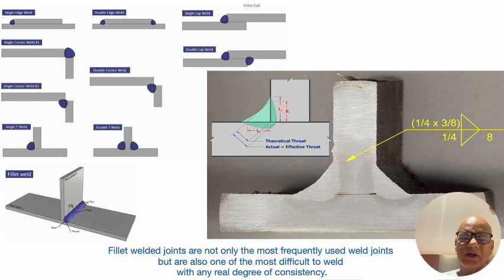and at the same time there are no defects. Like any other weld principle, if you cut right, you set right; if you set right, you weld right. That applies to the fillet also. We should put this vertical member on the horizontal member with as close a gap as possible, which means the edge preparation has to be cut correctly. The horizontal plate shall be as flat as possible, and we should fix it at 90 degrees, that is a right angle, on both sides, and tack it and ensure that it doesn't bend.